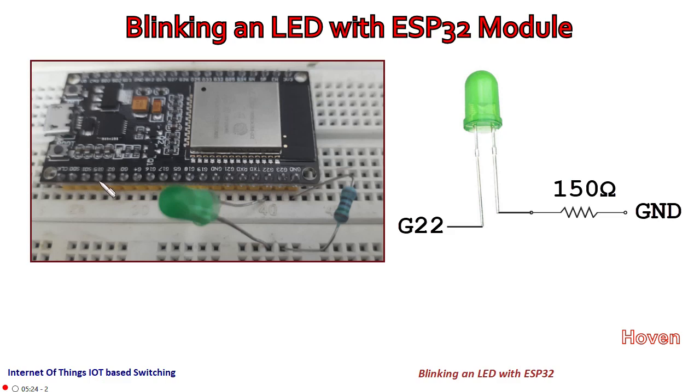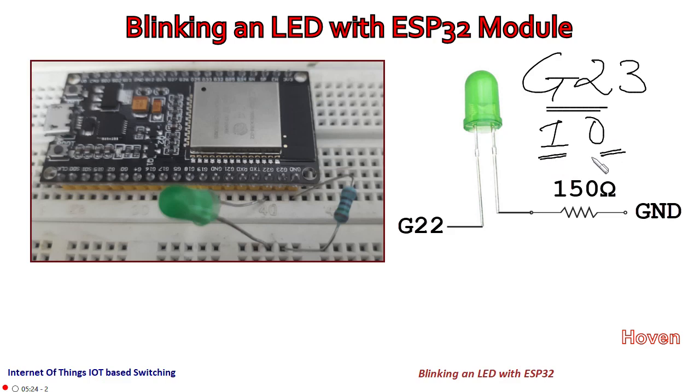So these are the various pin numbers, and whichever pin starts with G followed by a number, for example 2, 3, this is a pin which is meant for input or output. Input means you can connect a button or a sensor to it, and output means that it can provide a current, a voltage on it, so that we can turn an LED on or off.